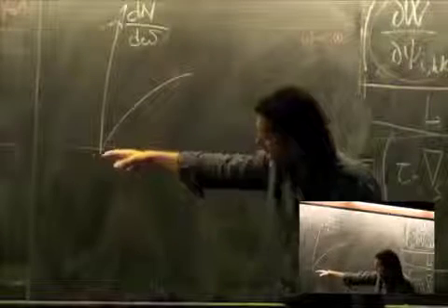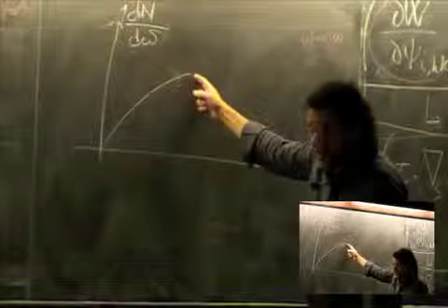It is quite obvious, even in structural engineering. One very particular exception is the case of the beam. In the beam, the natural frequencies have a gap that increases with the frequency, but it's the single case in which it happens. In general structures, the number of resonant frequencies for each frequency band increases with the frequency, up to a certain limit, of course,